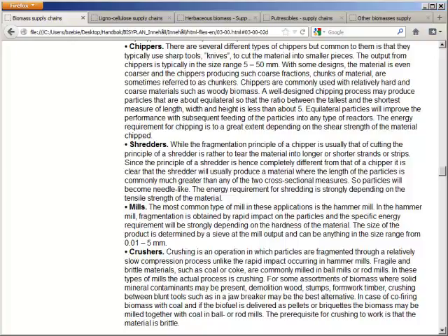The crusher is very often insensitive to contaminants, and hence nails or metal objects that might be present in, for example, demolition wood would not be a great problem in a crusher, whereas in, for example, a chipper, it would destroy the edges of the knives. The 4 different types of fragmenters have different roles to fill for different types of biomass.